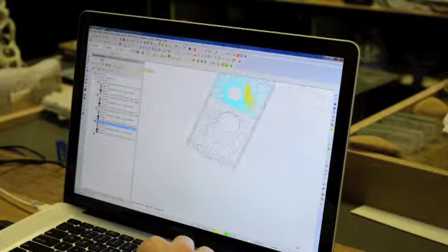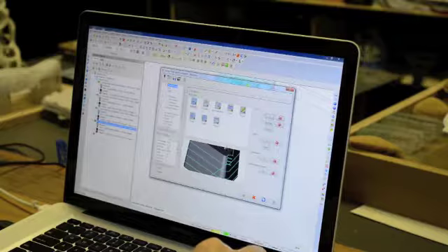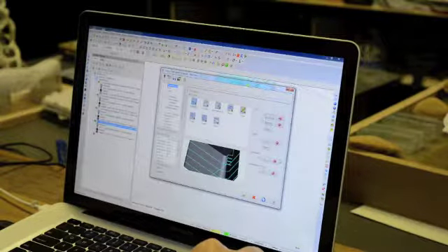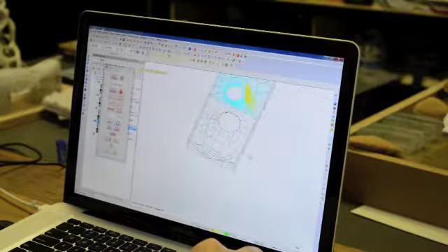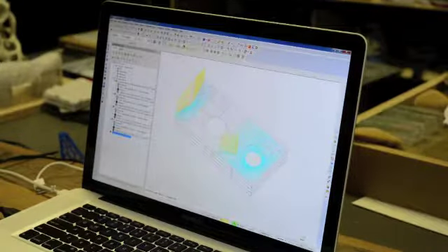A quick note is, after we ran the first simulation, we realized that our step downs in the finish pass of an 1/8 of an inch were not enough, so we cleaned those up to 0.03 inches to get the desired result. Do it live.